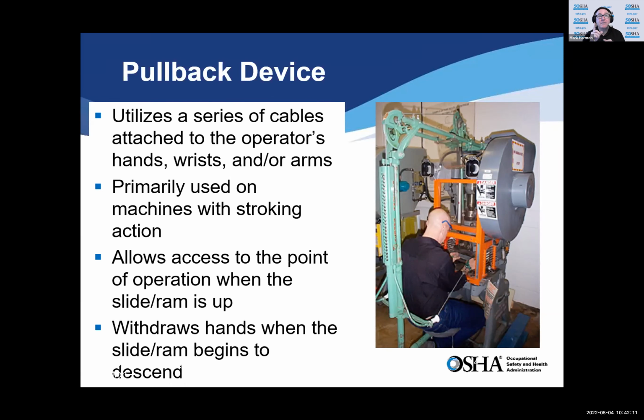I would say if you're using gloves in order to handle metal sheets, you should for sure think about that. If the parts that you have to put in the machine, if you can't wear gloves on the machine because of that fear of being pulled into it or being caught, then perhaps again think of, as we'd said, do you have a tool that you could use? But that's a good question. And if we need more information on that, let's talk after we're done today, and we can for sure help you with that in more detail.